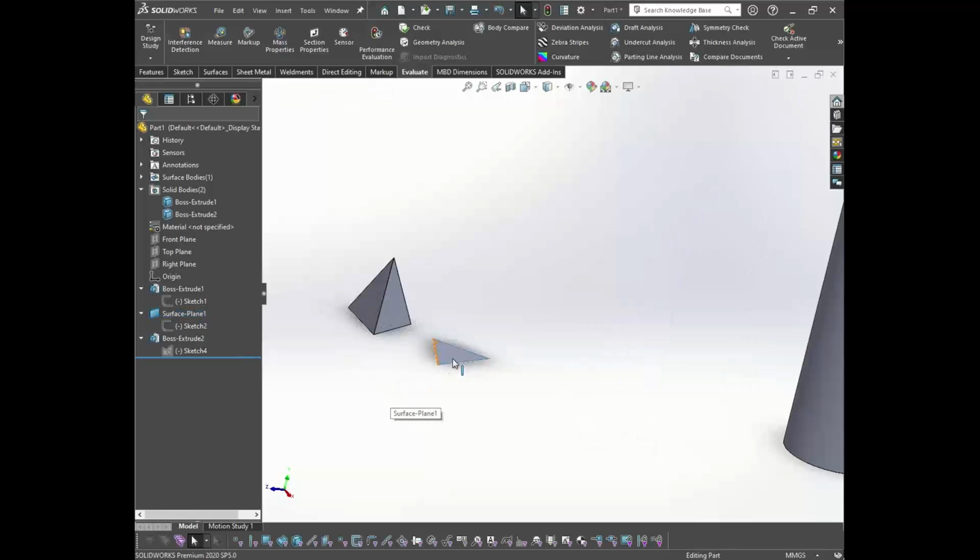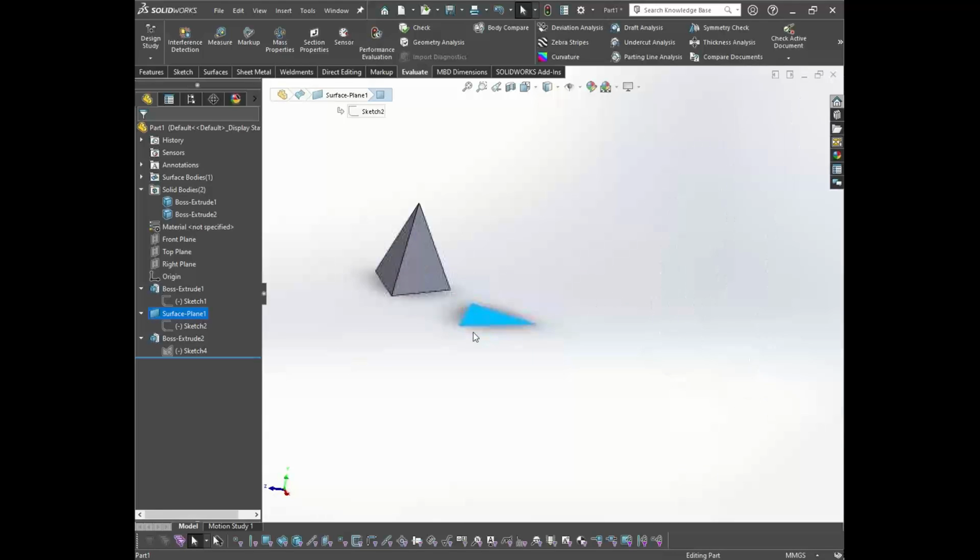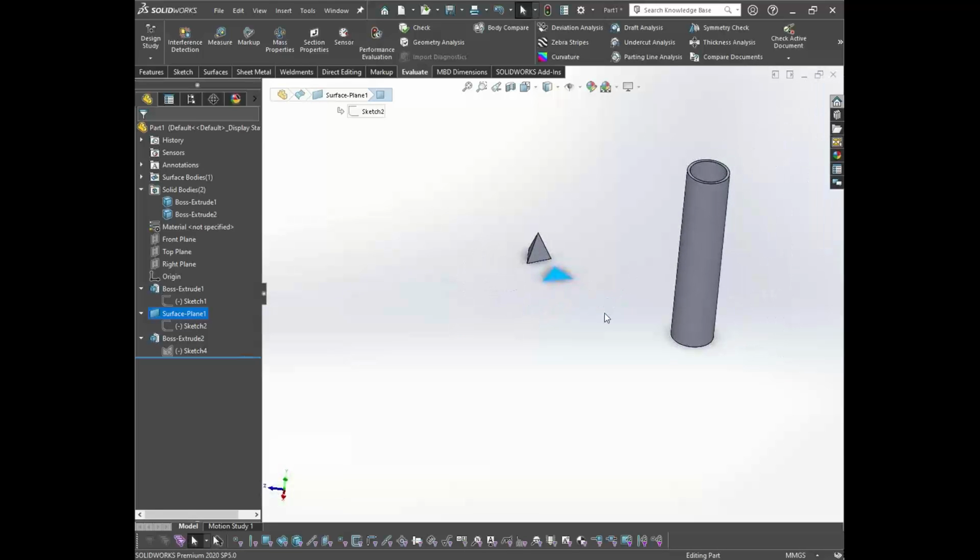For graphical representation purposes, it will be like this, a single sheet metal of no thickness. So the elements that would be created along the thickness will be omitted here, but the thickness properties will be considered in the backend. And for beam elements also, the cross-sectional properties will be considered in the backend. From a graphical point of view, we will only be able to see a single line with two nodes at the end. So is it clear?